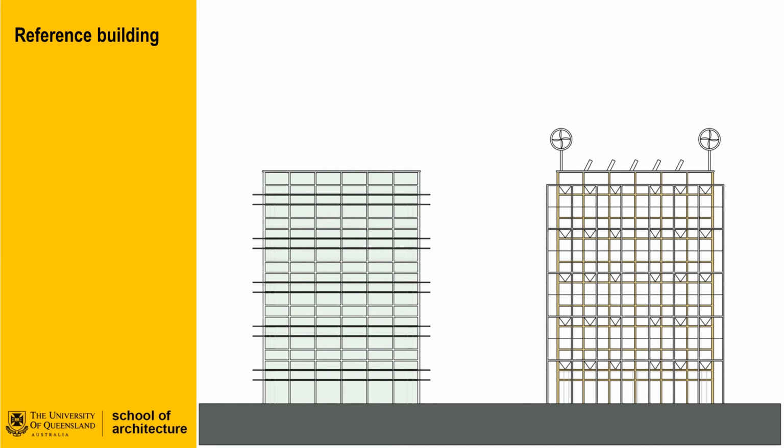When developing an alternative solution to comply with Section J, proposals are benchmarked against a reference building that complies with Section J. The alternative solution must on balance perform as well as the reference building, which opens up some scope for design trade-offs. For example, the alternative building may not perform as well as the reference building in some aspects, but may perform far better in others, which on balance results in a complying alternative solution.